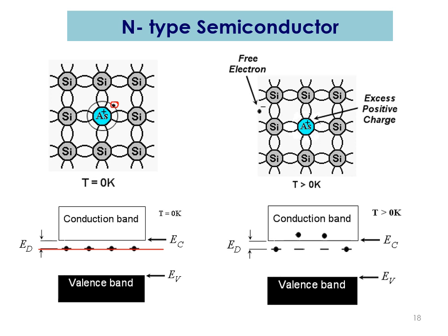We can see here the gap is shallow compared to the original energy band gap. There will be an excess electron here ready to be excited at T equal to 0 Kelvin. When the temperature is increased above 0 Kelvin, the electron will start to be excited into the conduction band.